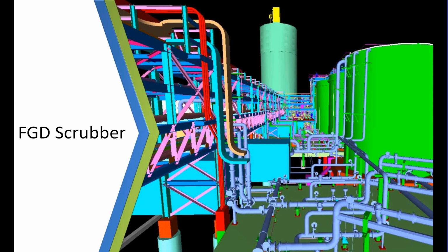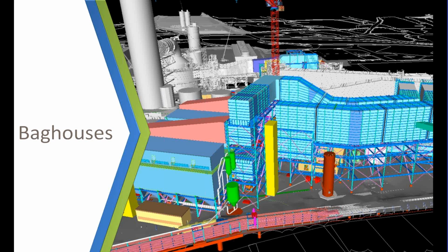Now, to further the good news, we started in fall deploying this technology on brownfield projects. We are deployed on an FGD scrubber, a flue gas desulfurizer scrubber project, also in Mississippi. We also went into projects around baghouses or MATS requirements projects in mercury control, which includes baghouses, activated carbon injection, and some other technologies to reduce mercury emissions at existing coal-fired facilities. And we are currently in production for 4 of these projects, with more to come over the next year.